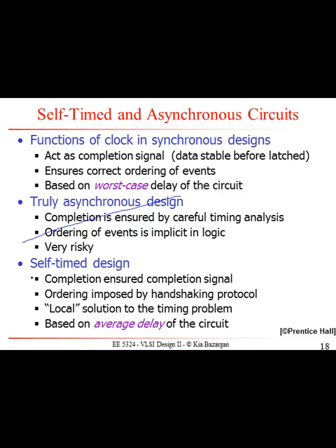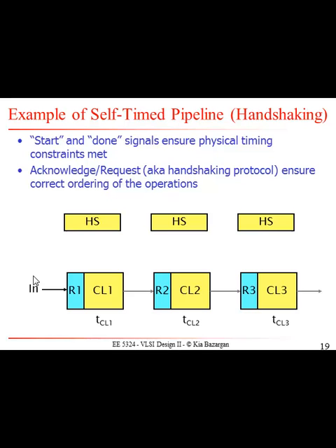We're going to talk about self-timed design, in which you don't have any clock signals, you explicitly create some handshaking signals so that each unit would tell the next unit, I have the data ready for you, start doing the computation on it. It's basically going to boil down to an average delay of a circuit, and as a result, it's going to become faster.